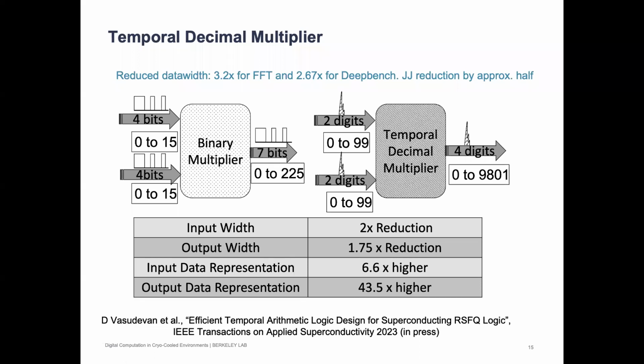And it's based on a really nice idea inside using lookup tables. And we can also save a lot of pin count. Another thing I didn't go into much before: because these chips are small and device density is so unfavorable, many of these chips are pin limited. So if we can come up with a new abstraction that reduces the number of pins we require to do computation, that's also helpful. And that's also what this is doing here.